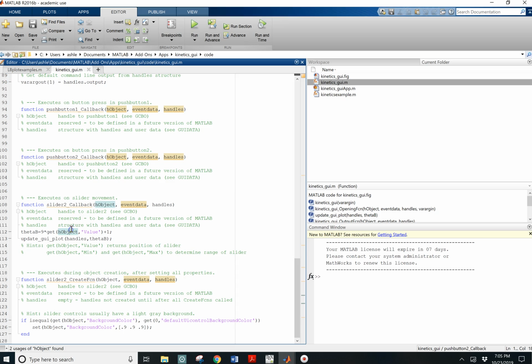It's just bulkier. So slider 2 is the name of the component that we used, and so we said 9 times the value, so the value is between 0 and 1, and we actually wanted it to range between 1 and 10. Yeah, it starts at 1. If the value there is 0, then this one's value is 1, so the ratio would go from 1 to 10. And so you could do other math to be able to use the information on the slider bar, or in the slider bar you can set its min and max in the property inspector. And so I can show you briefly how that works.